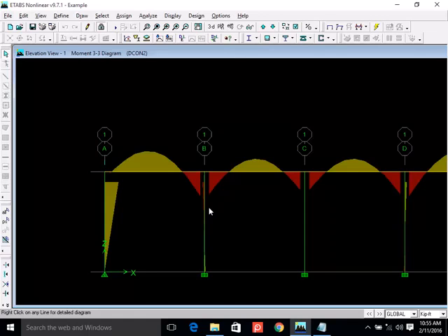Do you remember the coefficients for the design of continuous beams? The edge coefficient for the negative bending moment is smaller. If it is a hinge support, then it is 0. Practically maybe something. But at the interior support, you have significant bending moment. So at the discontinuous edge, negative bending moment is very small. But at the continuous edges, which are interior edges, you have significant bending moment, right?